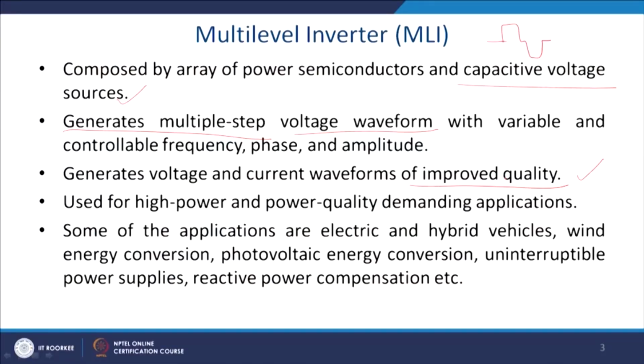So, it can have varied operations. You can have an active rectifier, and that can be made into the shunt active power filter anytime, because topologically they are not different. Once you take power to the grid and convert the shunt active power filter to charging a battery, then it becomes an active rectifier.